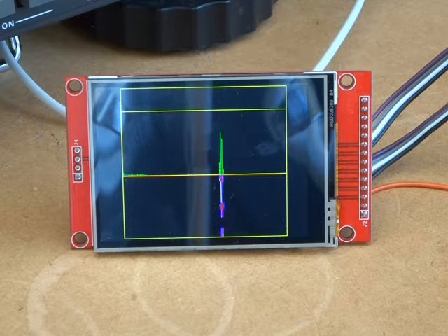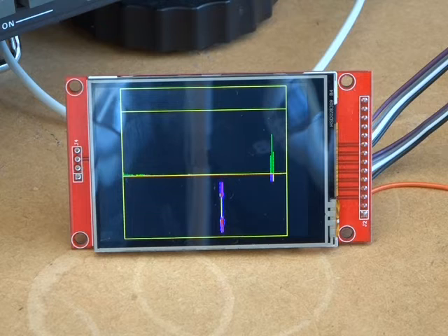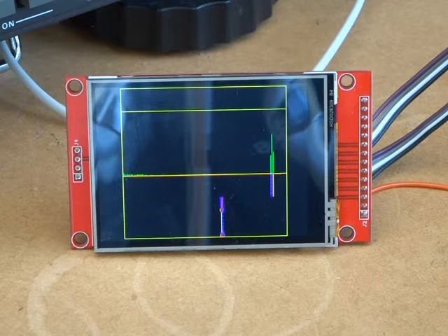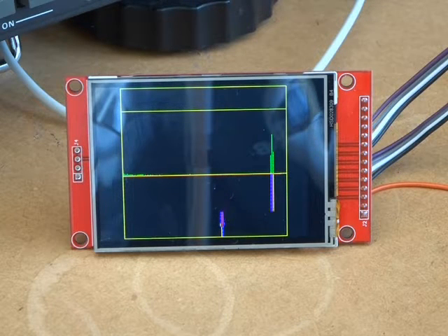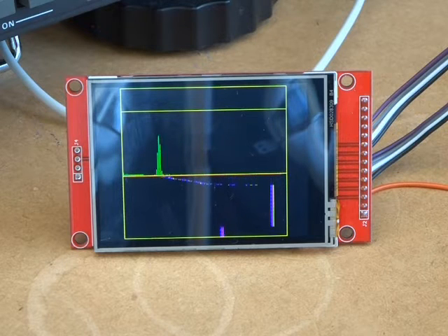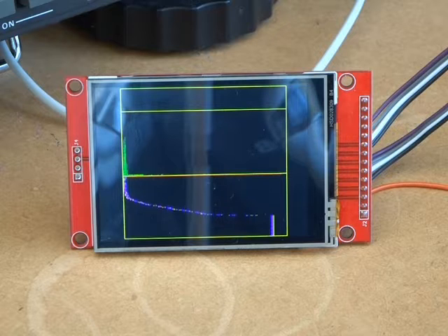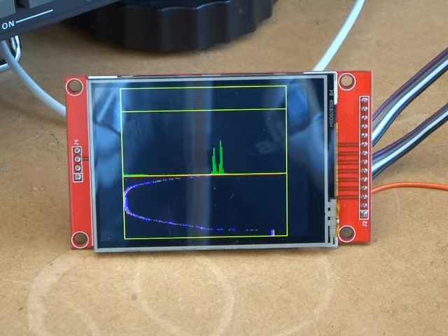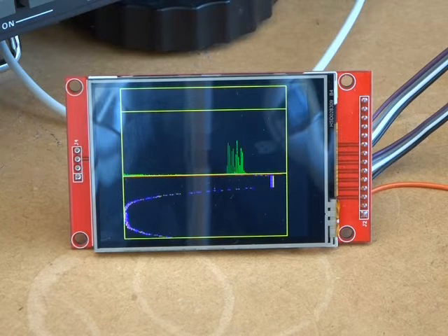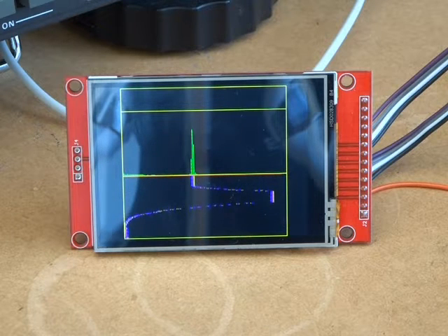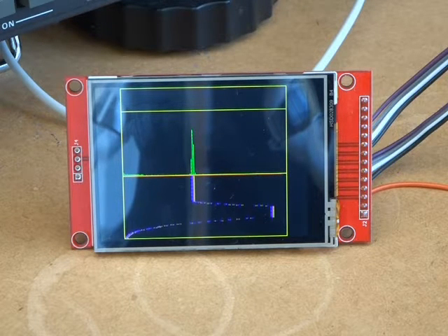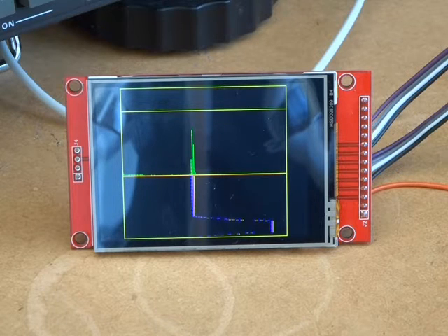Let's just put the amplitude up a little bit. So maximum it's picking up at the moment through the FFT is 20 kilohertz, which is there, and then we can wind that down to essentially DC, down to 0 hertz. So that's essentially all we've got to play around with, 0 to 20 kilohertz, being an audio analysis tool.